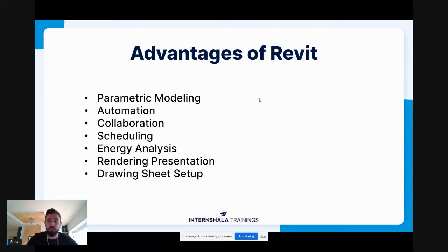First, we have parametric modeling. Parametric modeling is an all-inclusive phrase referencing the creation of 3D models from a set of rules. Revit uses parametric modeling via what are called families. Everything in Revit, from title blocks to 3D views to building components such as walls or floors, is part of a family. Some are built into the software, some accessible through libraries, and others are built from scratch. So this gives Revit models greater control over building design.